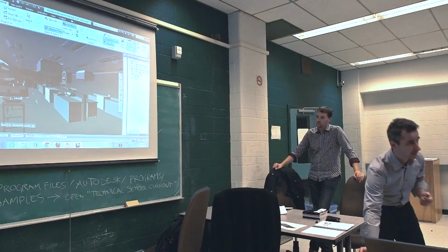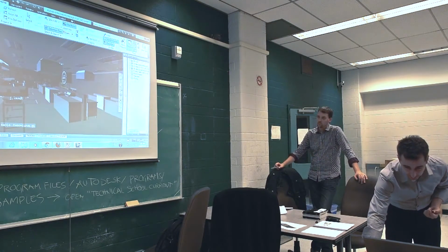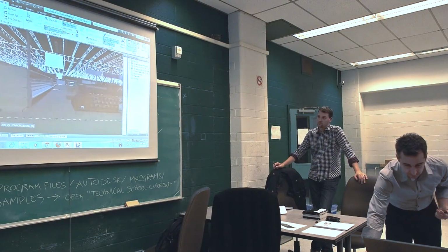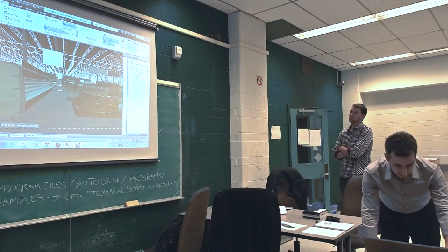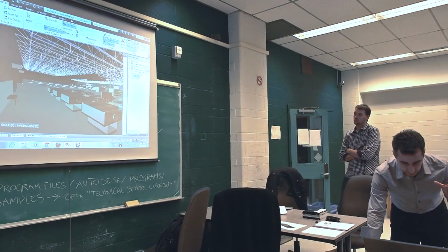So in Revit, you get another menu if you have Navisworks installed, and that menu will let you export to Navisworks. The result is up to 20 times smaller file size, and it comes down to an email-able file size. So you can email this to a client, or you can post it on Box. It's a previewer, so what they get is the actual 3D model. See, I put the shoes on and I move around. I have preset views in here. If I want him to look at certain things, I can preset these views and he can go look for himself.